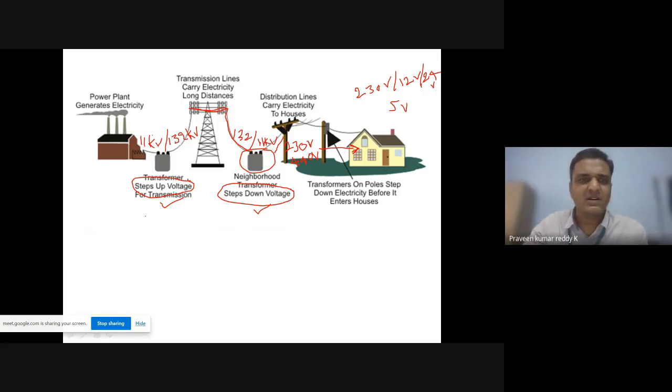So we classify these transformers into two types, or three types, you can call it. One is called power transformers. Power transformers are the ones used in the power system, at very high values, 11 kV by 132 kV or 132 kV by 11 kV, where the power range is very high. And this 11 kV by 440 volts kind of transformer, we call distribution transformers.